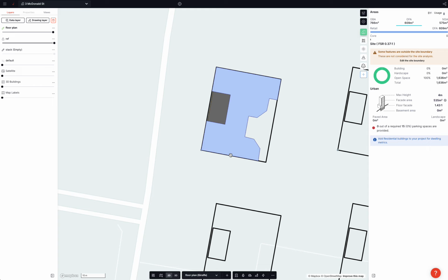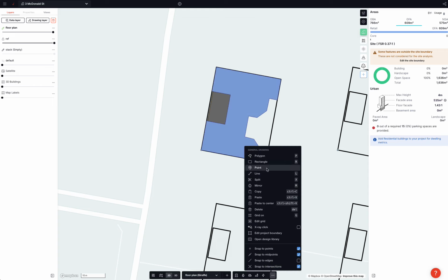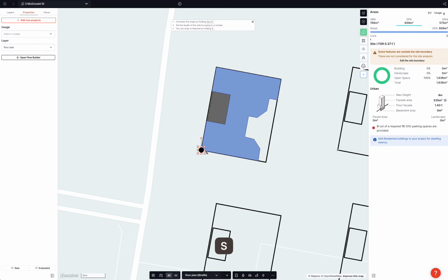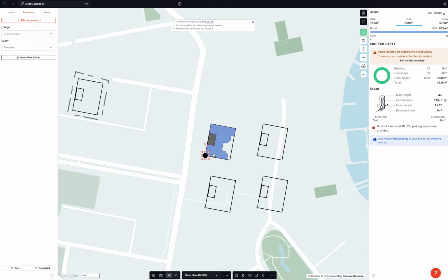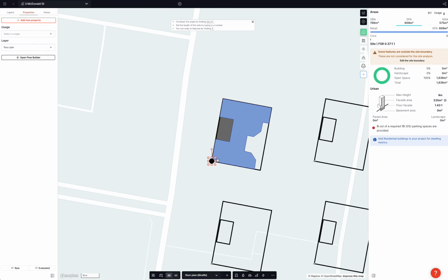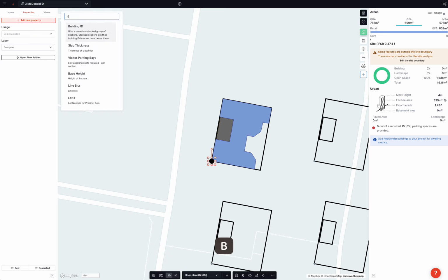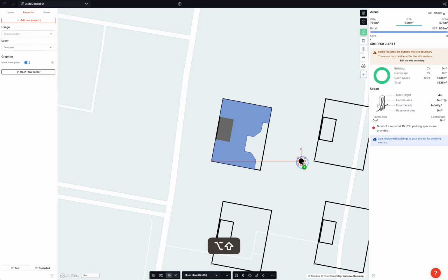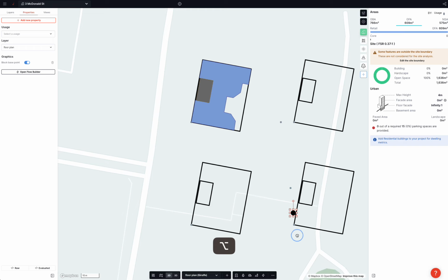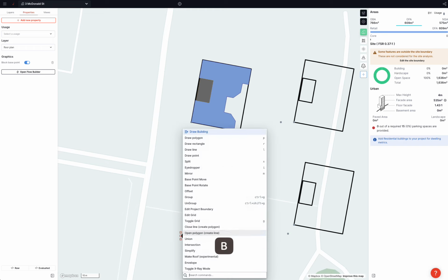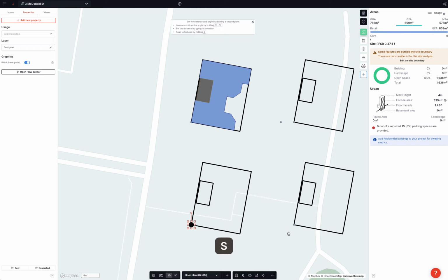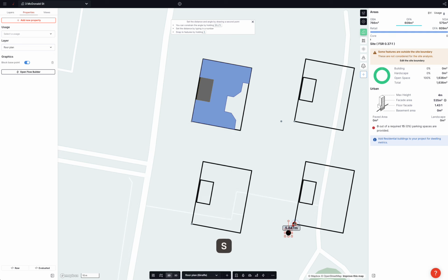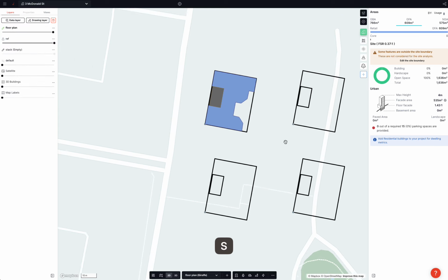And what I'm going to do here as well is I'm going to create a point again, and I'm going to snap it. And this common reference point is, you can see why I'm always snapping to that thing. And again, I'm going to add a property here called block base point. And I'm going to grab that block base point. I'm just going to copy it and copy it, and base point move it. Now, we don't have drag and snap working in the same motion, but when we do, my goodness, it'll be good.